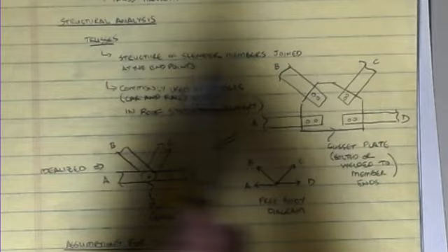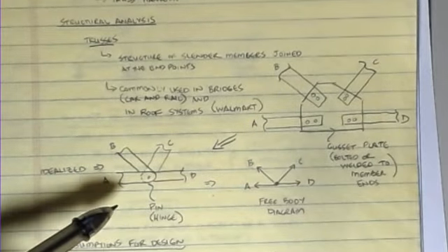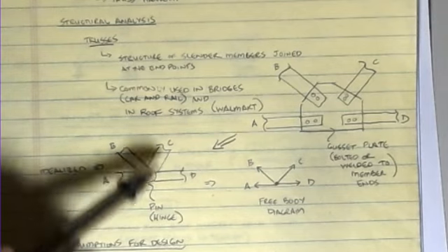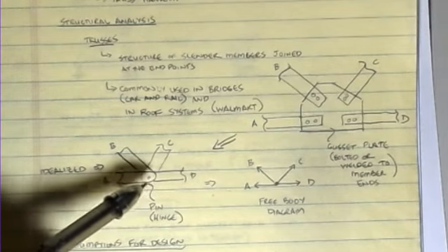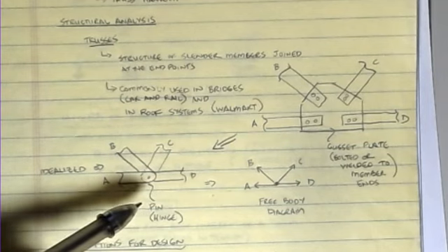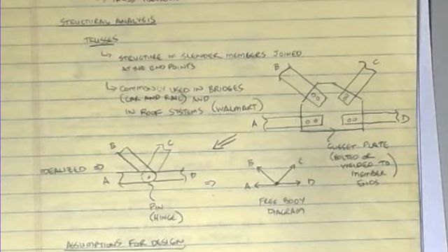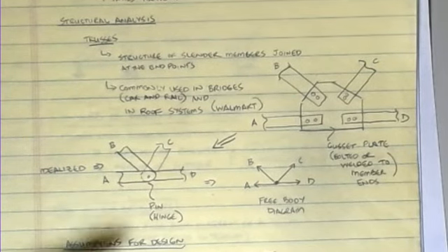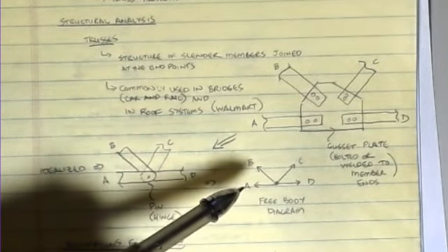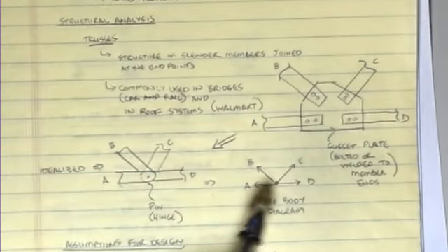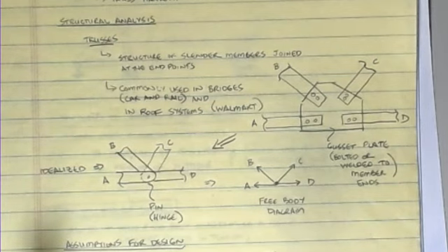And so what I can do is I can take this basic object and draw a free-body diagram in this case, and again, I'm assuming that connection is a common pin and that these members are straight. If that's the case, and if all the loads are only applied at the joints, which is typically the way those things are constructed, then my free body diagram becomes something that looks like that, in which all the forces are axial on these. Now, when I draw this free body diagram, it doesn't matter whether we assume tension or compression, because if I assume it backwards, we'll get a sign reversal in our equations, but we'll be able to figure out what the magnitude of the value is for that.